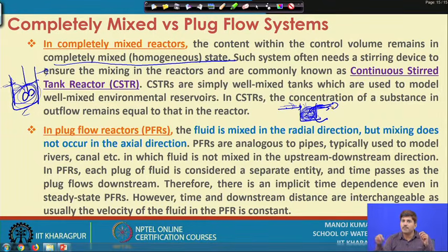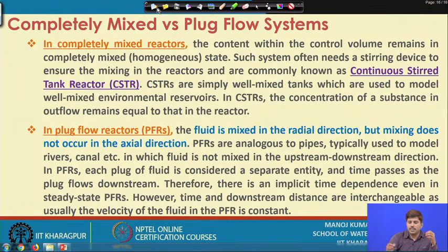So, if a lake is completely mixed and you withdraw some water from the lake through a channel, the water coming in your channel which is originating from the lake will have the same qualitative properties as the water within the lake, because the lake is completely mixed, okay. So, that is one of the basic assumptions of the CSTR, that the water coming out of the CSTR will have the same pollutant concentration, same contaminant concentration as the water in the CSTR.